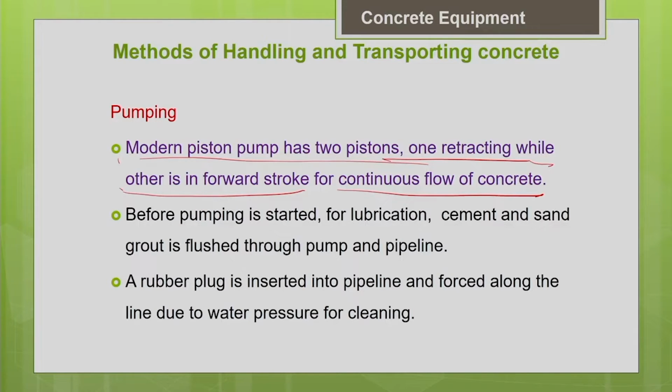Otherwise, your first batch of concrete pumped through the pipeline will lose most of its paste, which sticks to the sides of the pipeline, and the concrete delivered out will have less paste and more aggregate. So that batch has to be thrown out. To avoid that, and also because we need some lubrication on the pipelines to facilitate the easy and uniform flow of the concrete, the lubricating process is needed.